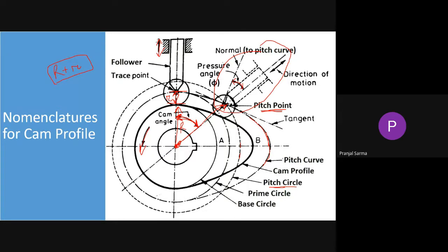Similarly, we know that during the course of working of that particular cam and profile, we design the cam to give a certain displacement or certain lift to the follower. The follower gets a certain displacement, and that displacement depends on the type of work that you need to do, so based on your requirement you design it. Now this lift or stroke, this is the similar kind of word that we use. Lift, or sometimes we call it the stroke.